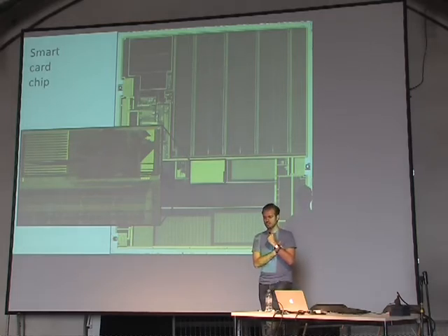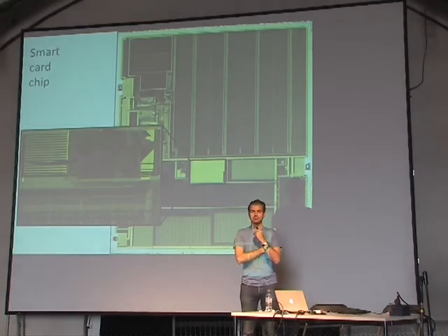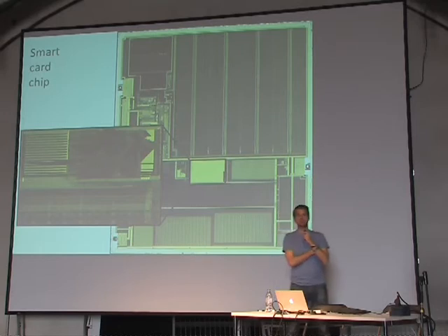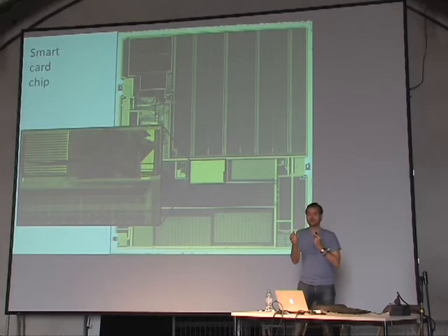No, it's more like a design process reason. So designing silicon gates and testing their functionality in all corner cases is hard work. So if you do this once for an XOR function and you prove that it works, then you don't want to do it again for the same chip. So there's a library of these very well-designed functions that people use. Just like you don't get to choose what assembly code you're using, Intel gives you a list of codes to use. So that usually comes from the silicon manufacturer.